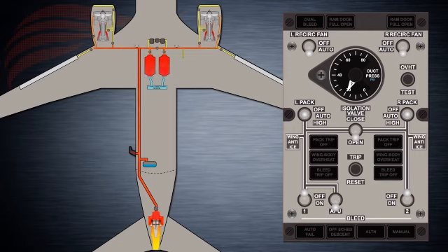In the case of engine-supplied bleed air, the thrust lever position has a direct incidence on the temperature and pressure of bleed air. If both the APU and engines are supplying bleed air to the pneumatic manifold, there's a high chance of it rupturing. The ducting is relatively thin, and therefore, caution must be exercised when selecting multiple bleed air sources for pneumatic power.